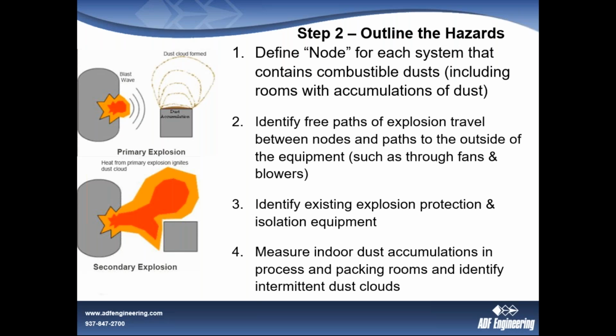Identify your existing protection and isolation equipment, make sure that it's adequate, and importantly, measure the indoor dust accumulations that you have, and identify those areas where you may be identifying higher levels of dust on the floors, on the rafters, on lights, and so forth.